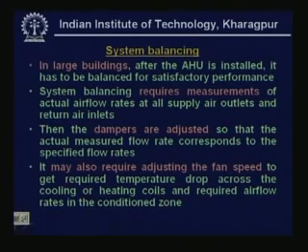Ultimately, why do we do system balancing? Let us say that you have carried out the cooling load calculation, designed the ducts, selected the fan, and installed everything. Finally, you have to get the required performance, that means you have to get the required temperatures in the conditioned space. This depends upon the temperature of the supply air and also upon the supply air flow rate. So, you have to make sure after you install everything that you are getting the right amount of air at the right temperature. Since several assumptions are involved at the time of design, it does not happen automatically. So, some kind of adjustment is required to get the required conditions.